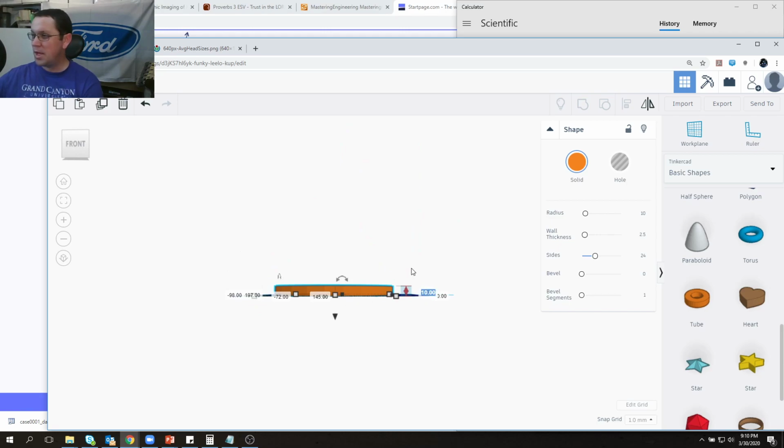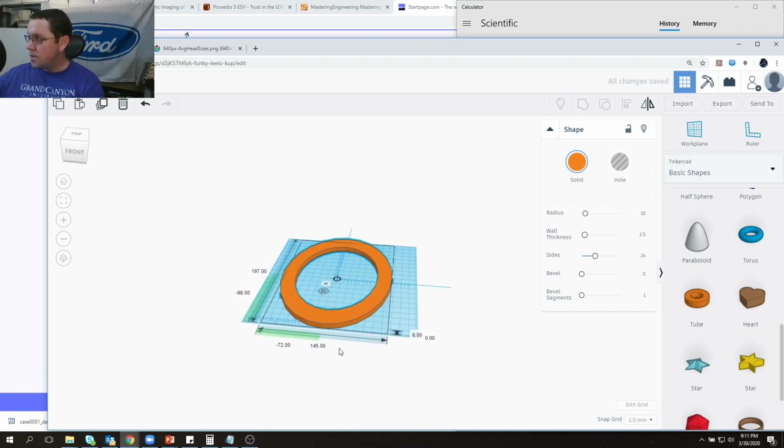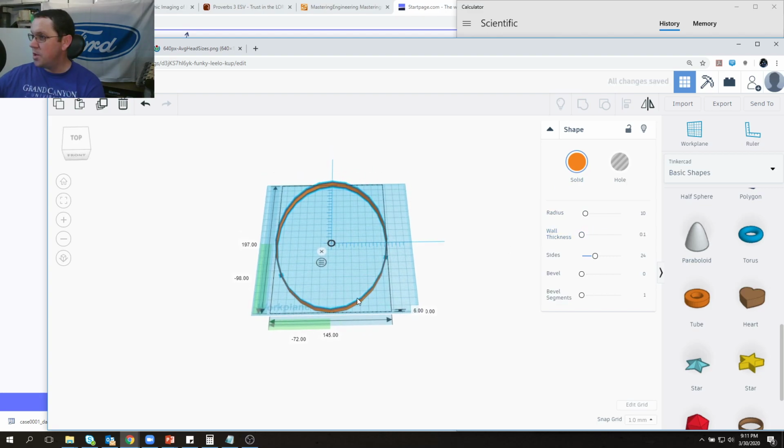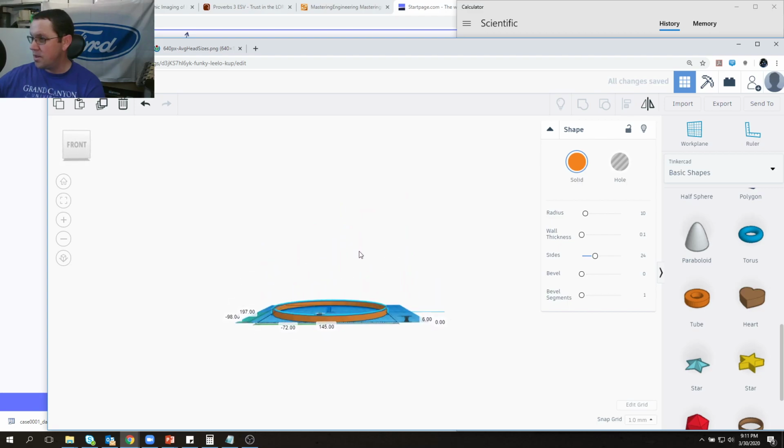We may want to trim that down just a little bit, because we want to think about if you're going to be wearing this all day long in a regular environment, you want to keep it fairly narrow. So we probably want this to be closer to something like 6 millimeters. So we just type 6. And then for this, you can tell it how many sides and some of the other things. The wall thickness can be much, much larger or much, much smaller. So we don't want this to be really sort of an infinitely thin band.